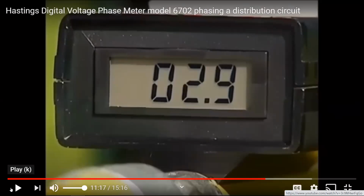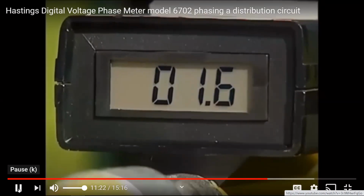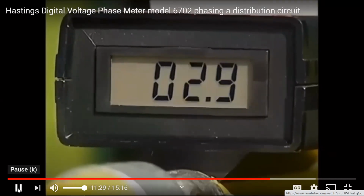Starts high, goes down, goes back to high: punctured cable. That is a bad cable. It's fluctuating, accepting the charge and then discharging it. So we have 3 situations. We have a good cable, a fully faulted cable, and now a punctured cable.